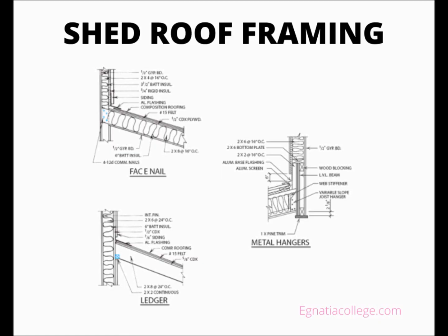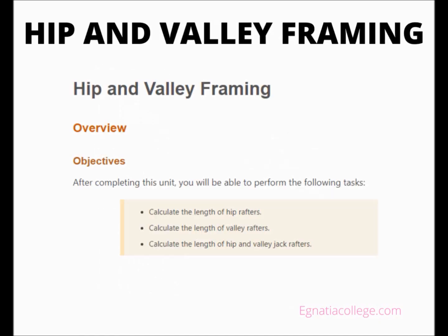It is often necessary to frame openings in the roof. Where chimneys, skylights, or other features require openings through the rafters, headers and double framing members are used. This method of framing openings is similar to that used in floor framing.